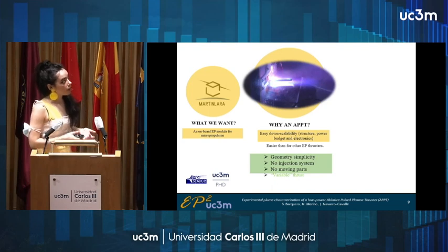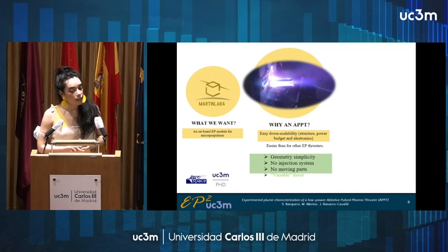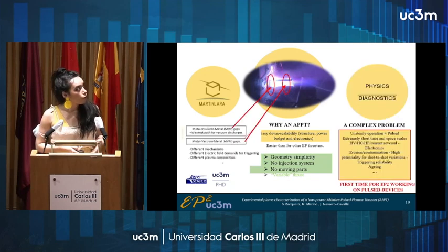So we have these advantages, as I said, and it is also very versatile because we can modify the thrust just by varying the firing frequency, but it is not free of problems. Because we have to deal with many fields, and also because the physics behind the generation and acceleration mechanism is not clear. So this is a real challenge for EP2, as this is our first time working on pulsed devices.